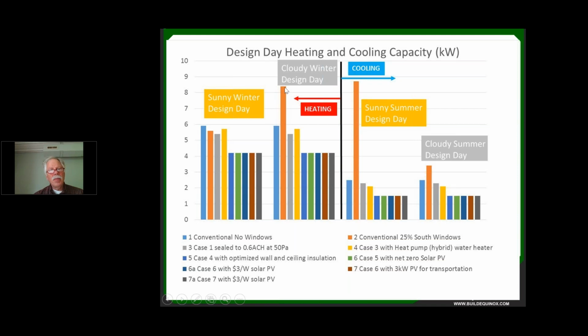But when it's cloudy or at nighttime, and we've got data from homes that are windowed in this manner, I can tell you as soon as the sun goes down, the furnace goes on. The temperature inside drops like a rock, and I don't care how many tons of extra concrete you've dropped in, how massive your brick or stone chimney is inside, how much phase change material you've thrown in there, it will drop like a rock, because even though those might have some energy stored, you can't get it back out at the rate needed as you overwindow a house. So this house is going to require substantially more heating capacity than this house without windows. And cloudy days and cold days do go together. So this is going to happen. No ifs, ands, or buts about it.